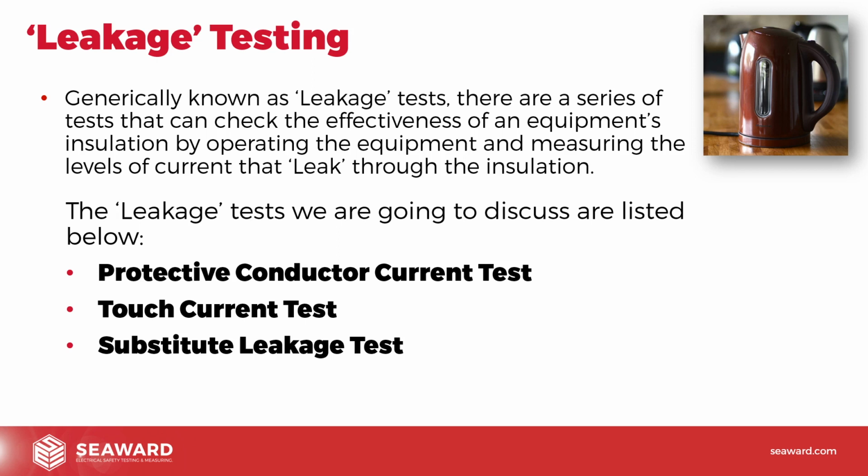We're going to have a look at what's called the protective conductor current test, the touch current test, and the substitute leakage test. These are all generically known as leakage tests, and there are sometimes different names for these, but those are the current names as they're listed in the code of practice. You will sometimes see some PAT testers and manuals refer to them by different names, but they're generically known as the leakage tests.